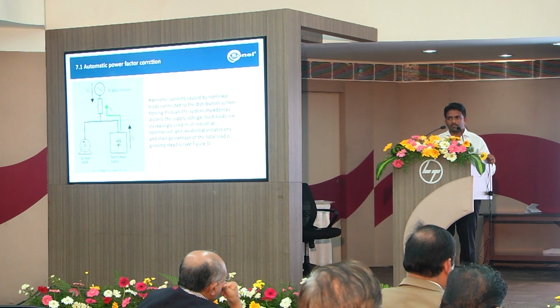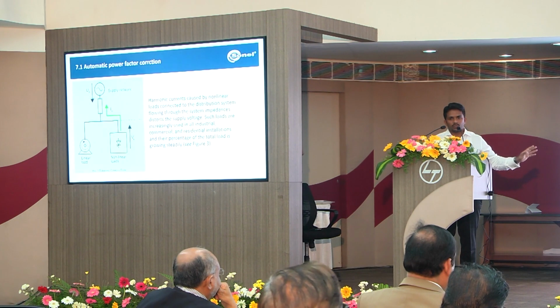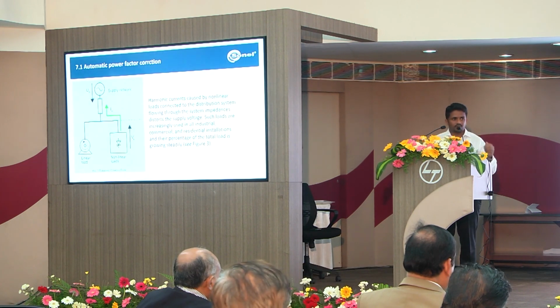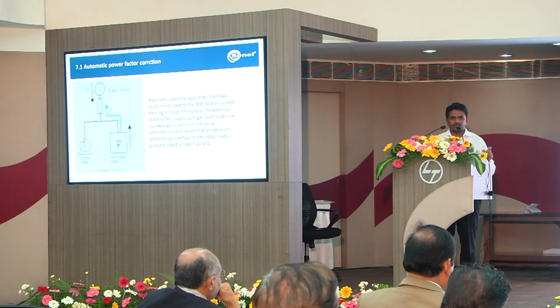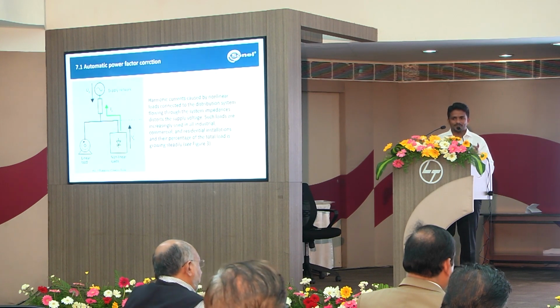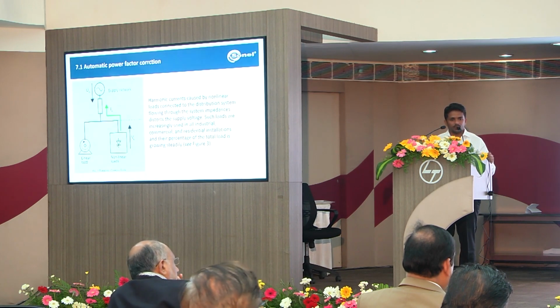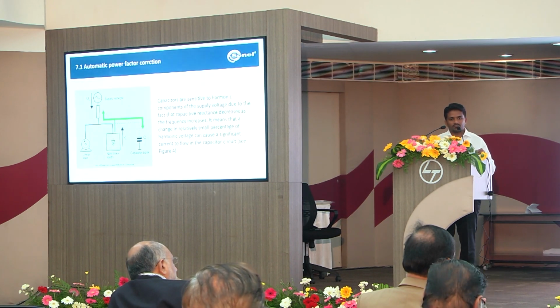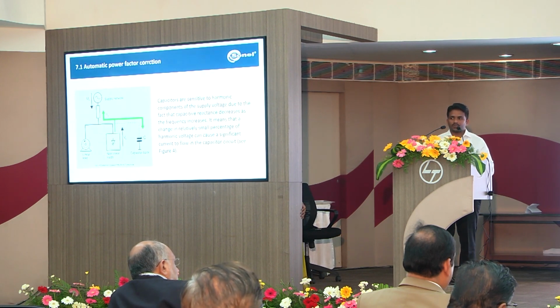So this is an extract from the NEC document on power factor correction. We know a non-linear load is going to generate, the word generate, it has been infused in me for many years. It's not generate. The word that is used in NEC, I like this word. They used a word called cause. The non-linear load causes harmonic current, because all these days I'm repeating generate. We know it is not true, but this is what is written in the standard. So the harmonic current which is caused by a non-linear load, when there is a capacitor, we know because of the capacitive reactance, the capacitors are prone to have a problem when there is a high harmonic current.